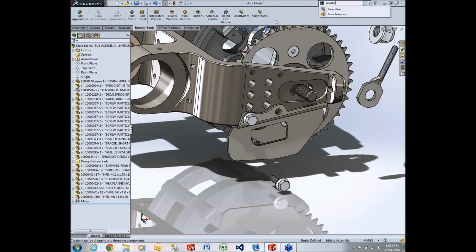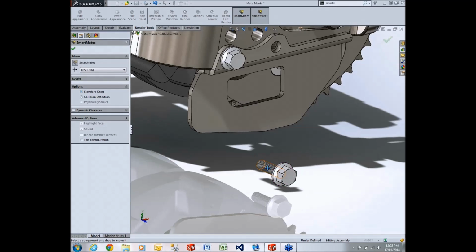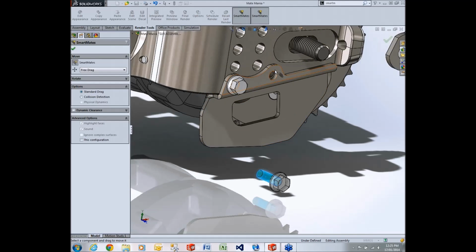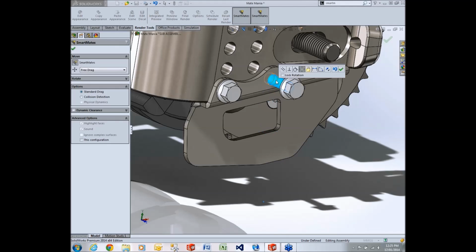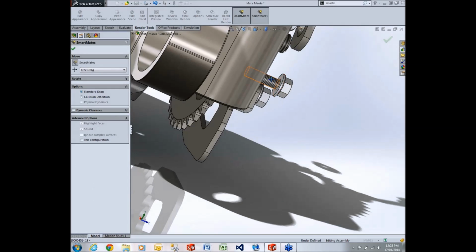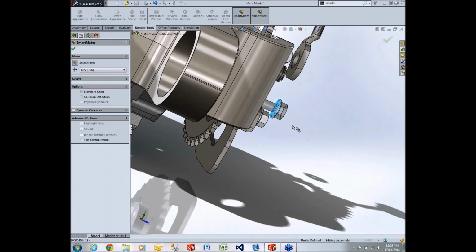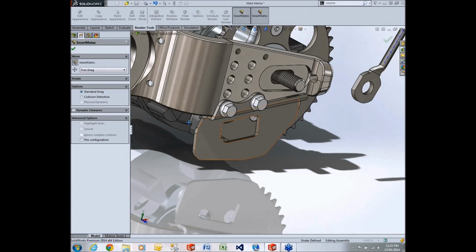So we can drag that command onto any toolbar in SolidWorks, and I can now click on that and double-click on one face, single-click on a second face, and apply it, lock the rotation, hit OK, rotate around, double-click on this face here, rotate back around, single-click on this face, and we'll apply that concentric mate.